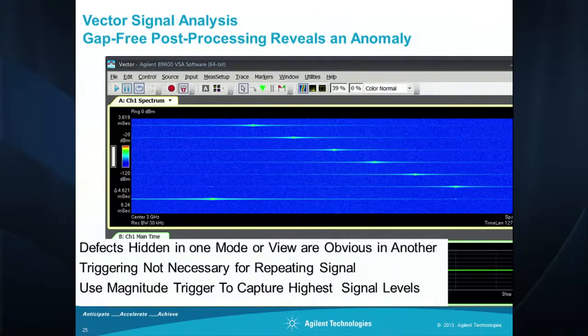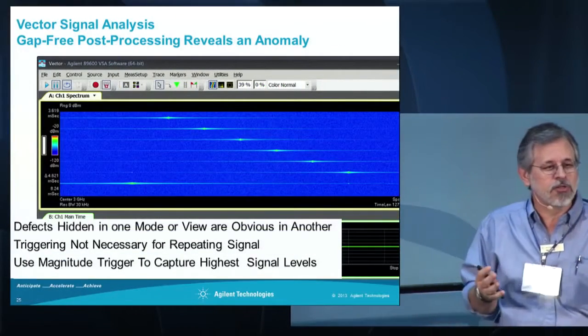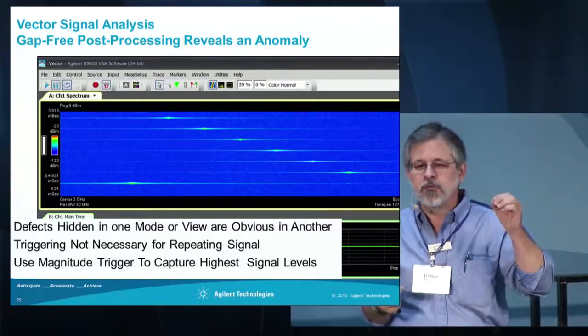So what's happened here is a fairly simple thing to do when you're assembling your signal. Your interpulse group interval, that delay, was put after the first pulse rather than before it. Simple error to make, but it'll confuse your radar, and you'll never see it in swept and most real-time modes. And yet when you do a capture and a playback, it's completely obvious. And now, of course, we can go back and individually demodulate those if they're modulated pulses.